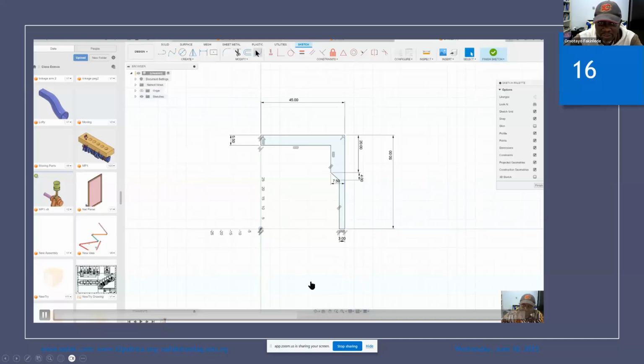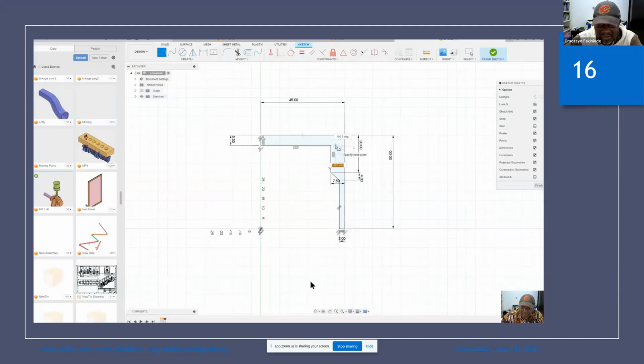So you move about 4 units down, you take your line tool, move about 4 units down and come in, and then do a close rectangle there. Do another one there. Come in, do a close rectangle, second close rectangle, and then make another one, and then do a third close rectangle. So we are going to use the constraining and dimensioning tools to force those things to be the way we want. So the first one is 4 units from the top.